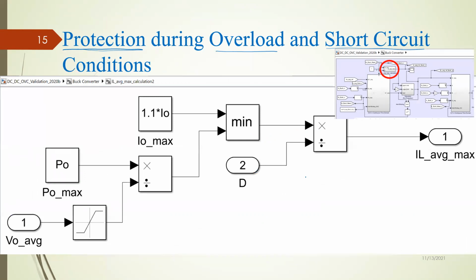Let's say this is your converter, this is your DC to DC converter, and this is your load, and you have a source here. It may happen that the load draws more power. If the load draws more power, then there will be more power flowing through the DC-DC converter. It can be greater than the rated power for the DC-DC converter, and hence your semiconductor devices, inductors or capacitors could fail. So we need to limit the output power.